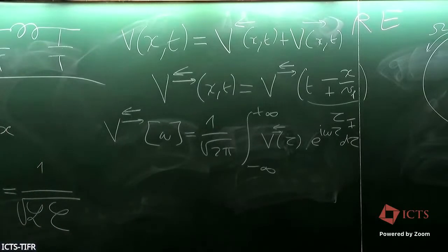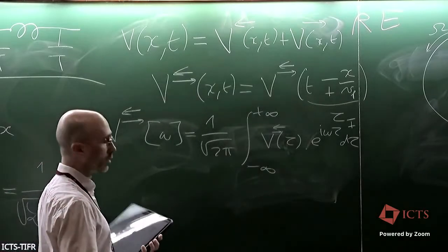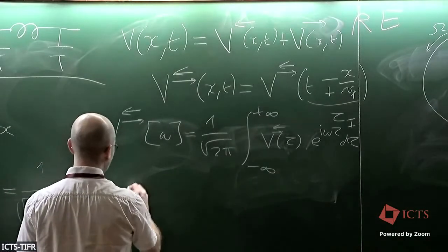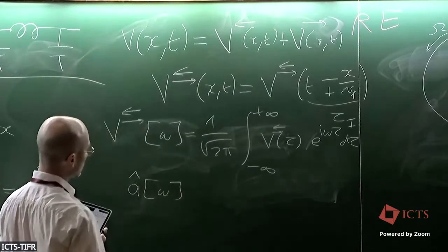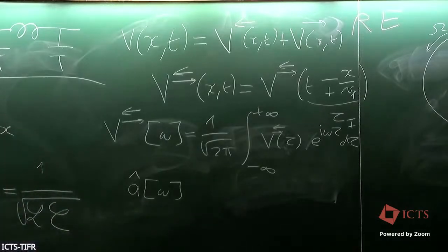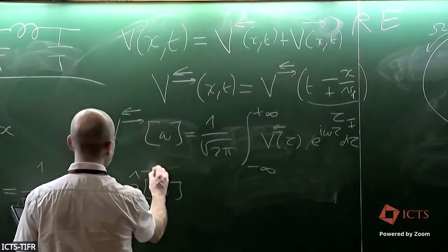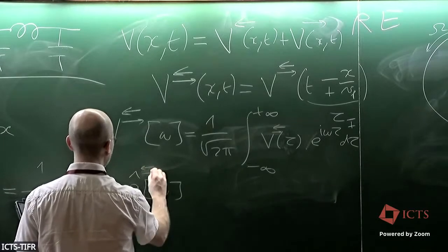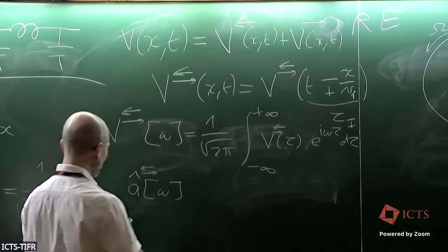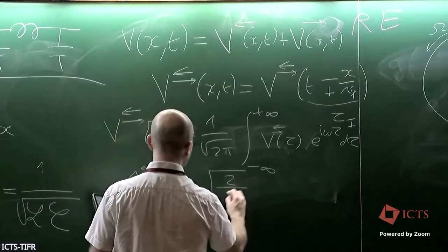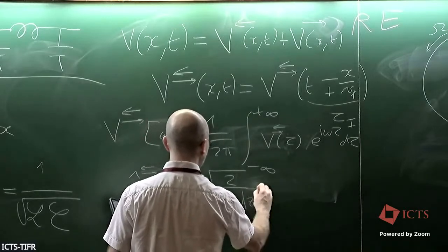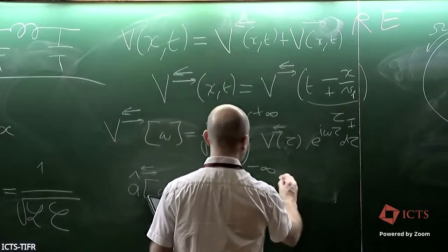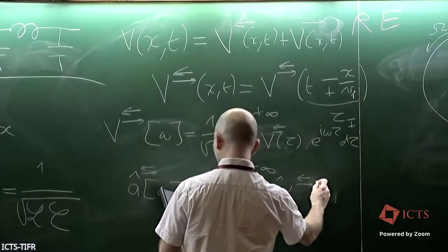And so with this, we will define the amplitude, which we will now put a hat on. So the complex amplitude, which is analogous to somehow an annihilation operator, as you will see, that corresponds to left-moving or right-moving waves, is simply defined by the square root of 2 over h bar omega Zc, the characteristic impedance, times the voltage operator, this propagating voltage operator.